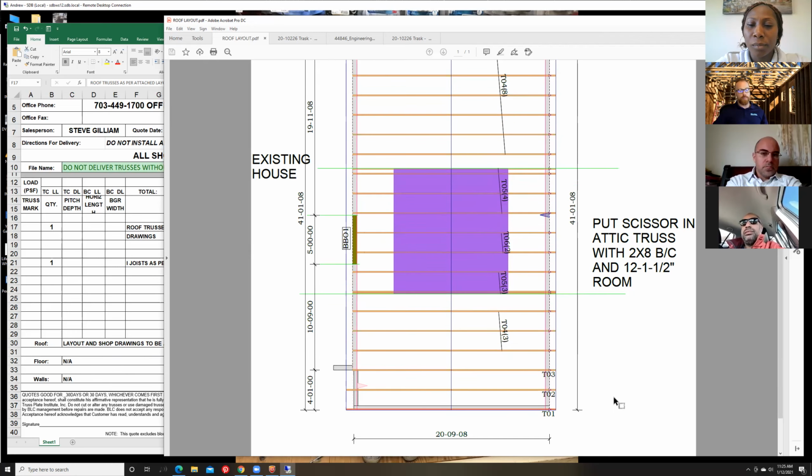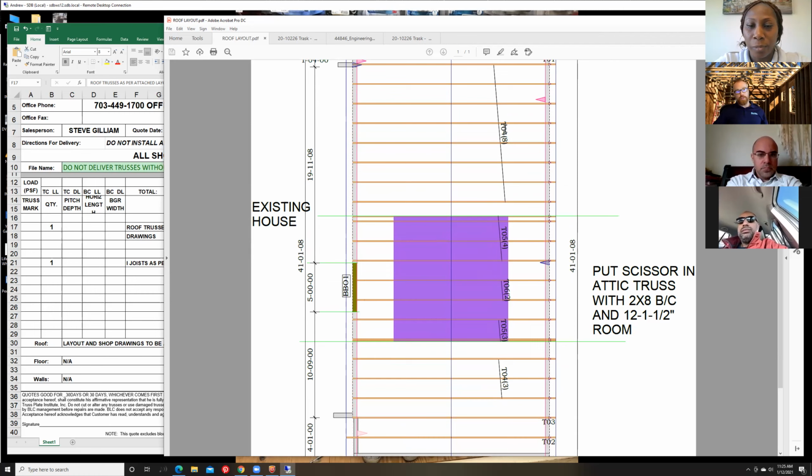So they're their own separate trusses, but they're their own. We'll go take a look at what those look like. Andrew, just for clarity, when you say trusses are the same, how do you know? Is that because they have the same number, like TO1? That's right. There's a TO4, and there's 8 of them, and there's TO4s here, and there's 3 of them. So we know that they're the same number. You can reference that page, and I'll do that. But that's basically the coding number and the quantity.